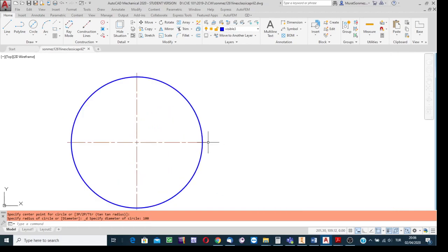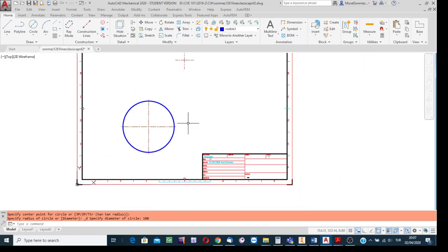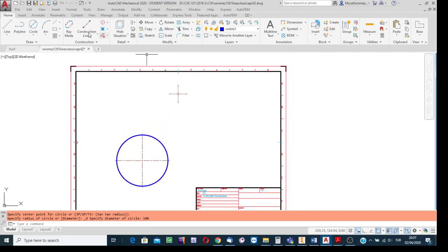Actually, AutoCAD, in creating the symmetry axis, asked me the diameter. So, using that diameter value, it created the symmetry axis in the correct order. You know the agreement. Symmetry axes are to be created in a length having further extensions. It is a must. So AutoCAD in the background satisfied that format requirement and created the symmetry axis in the correct order.